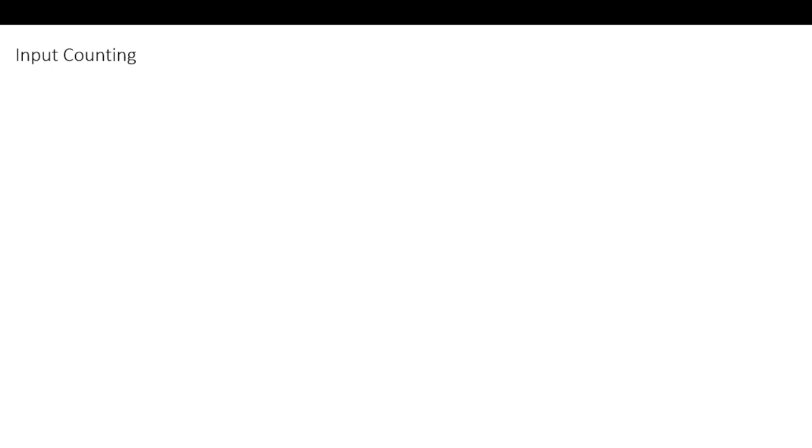So next, in the input counting method, we will count the changes in the values, so we update a counter. Say now, if some gate input switches from 0 to U, and we consider this gate to be a NAND gate, the input has changed from 0 to U, so the count of the controlling inputs is decreased, whereas the count of unknown inputs has increased.